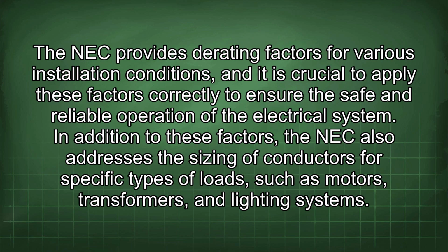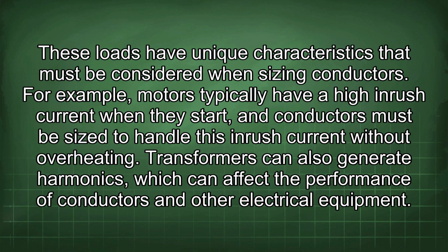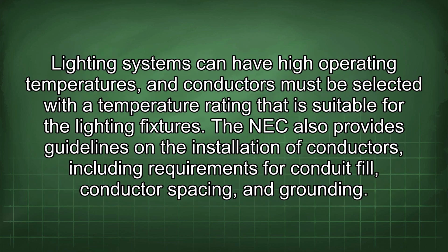In addition to these factors, the NEC also addresses the sizing of conductors for specific types of loads, such as motors, transformers, and lighting systems. These loads have unique characteristics that must be considered when sizing conductors. For example, motors typically have a high inrush current when they start, and conductors must be sized to handle this inrush current without overheating. Transformers can also generate harmonics, which can affect the performance of conductors and other electrical equipment. Lighting systems can have high operating temperatures, and conductors must be selected with a temperature rating that is suitable for